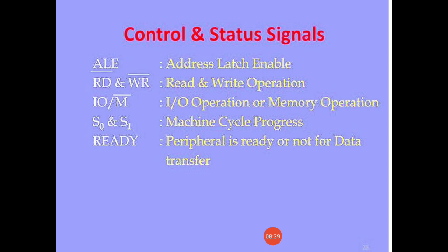So the latching of the lower half of the address bus is done by using an external latch and the ALE signal from the 8085 microprocessor.